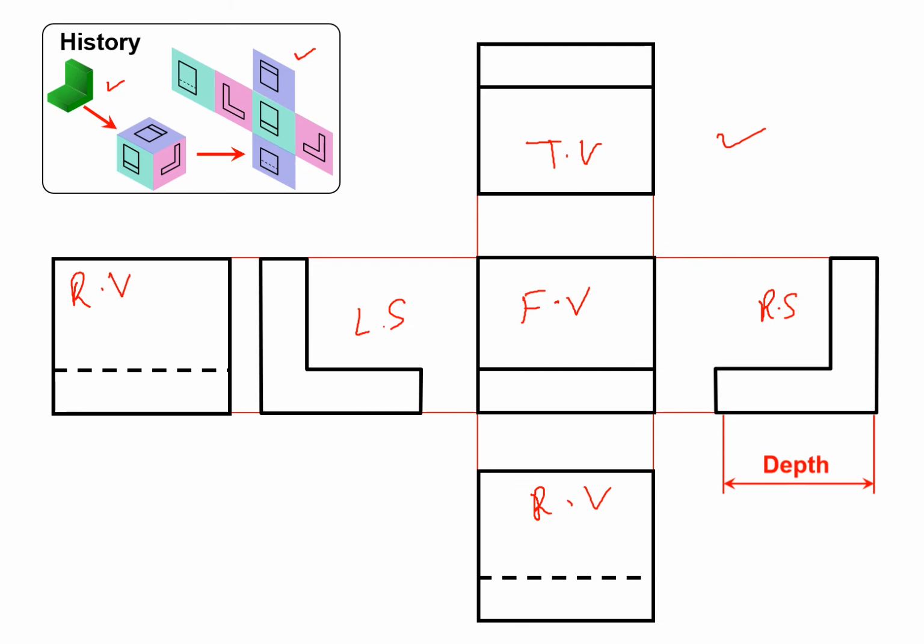And this is another concept that is called the glass box concept. One was the orthographic projection concept, the parallel projection concept, and this is another concept in which we place our object inside the glass box, and then we project the faces of our object onto the planes of the box, and then we unfold the box to get our 6 principal views, and then we select only 3 views which are enough to give us our information of size and shape of our object.